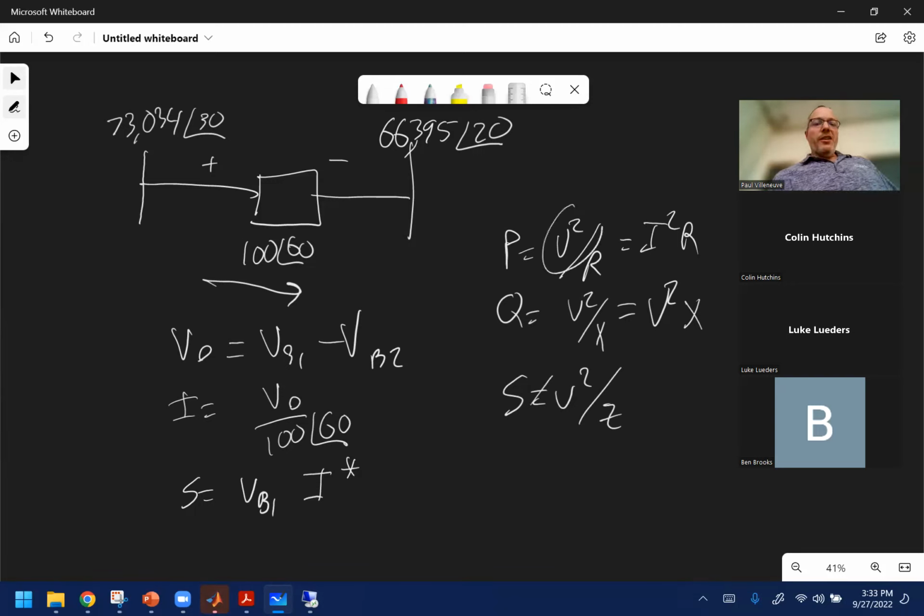Because if you recall, this number V is a magnitude only. This has to be the magnitude of the voltage. It is not the magnitude and the angle, because if you square it, you're going to end up with a P that has a real part and an imaginary part, if you include the angle. A lot of people put on the test, the power equals 3,552 plus j7,638 watts. How can you have a j term and it be real power? S could be that, but not P.